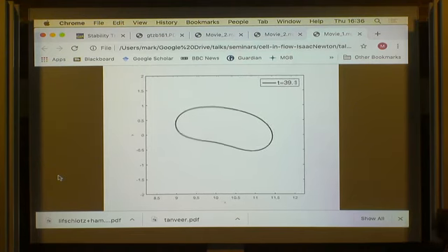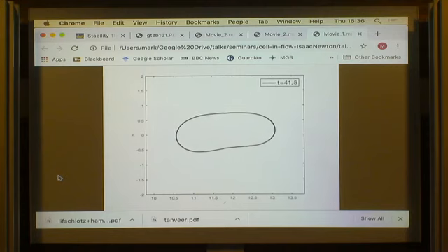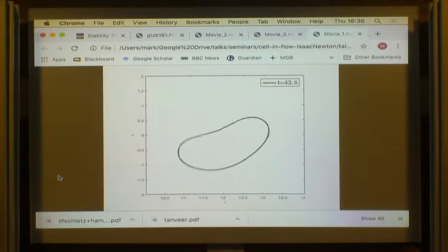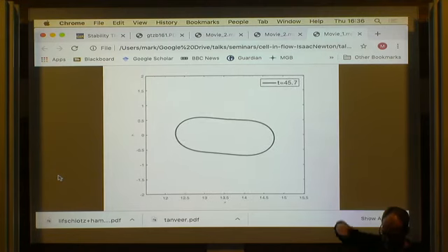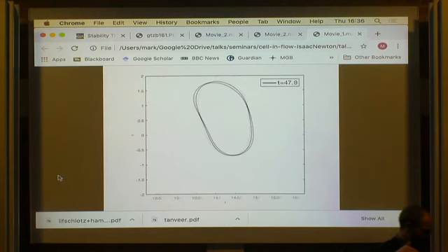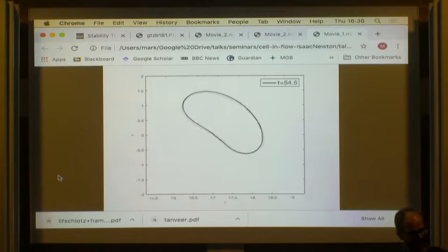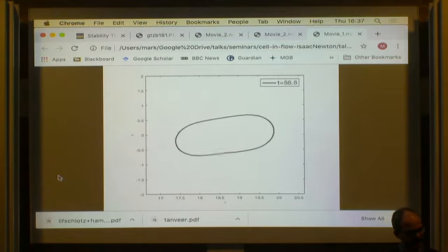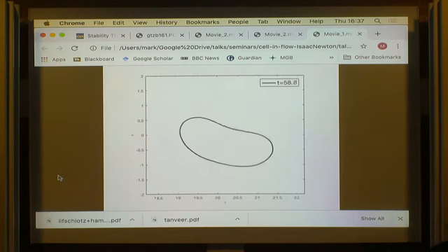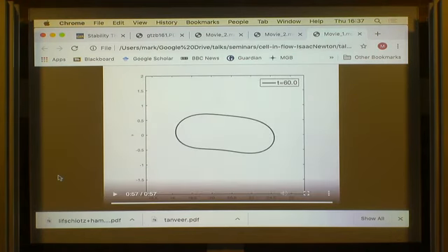It's kind of fun. Mark, is this motion periodic? It's not periodic. If you look at the wall carefully, there's a little bit of a wobble. As far as we can tell, we didn't look at this very closely, but we computed the Lyapunov exponents for this calculation, and there's some evidence that it's chaotic. It's either chaotic or quasi-periodic. We haven't looked at this really carefully, but it's not periodic. If you look at the time signal of, say, the bending energy of this thing, it's pretty clear it's not periodic.